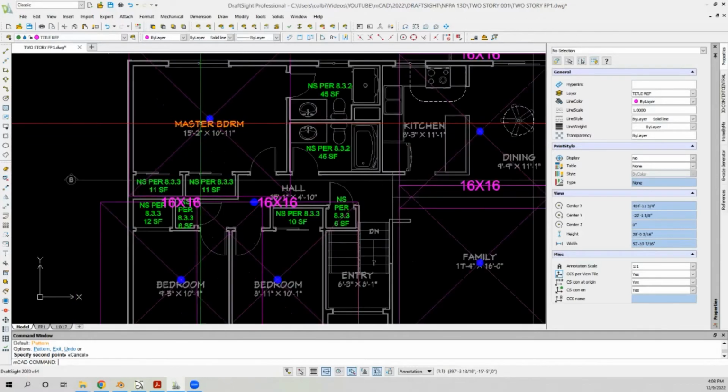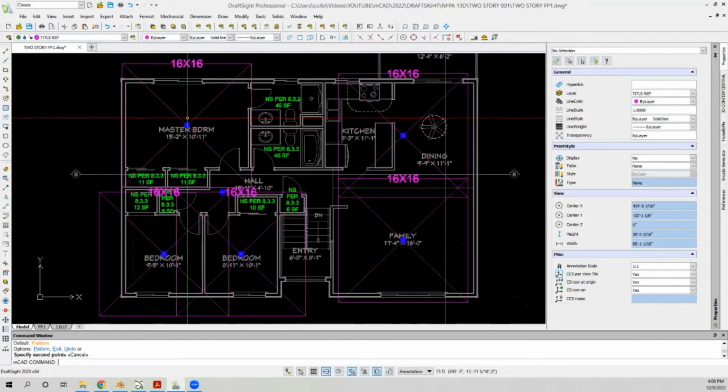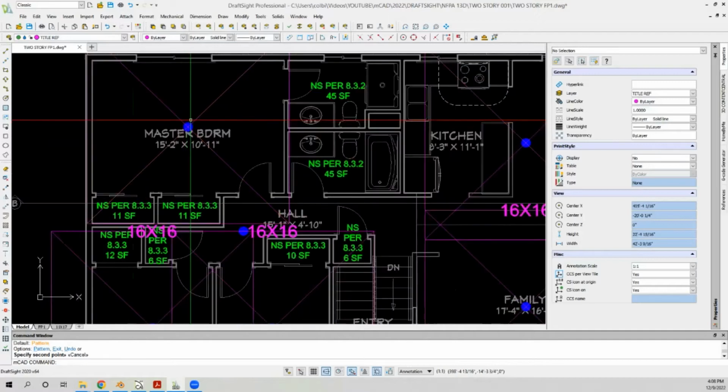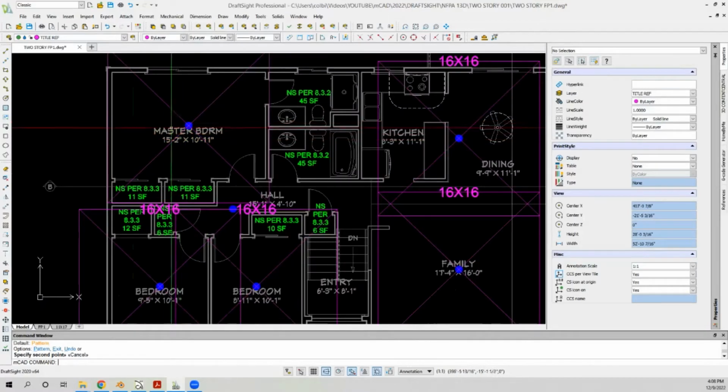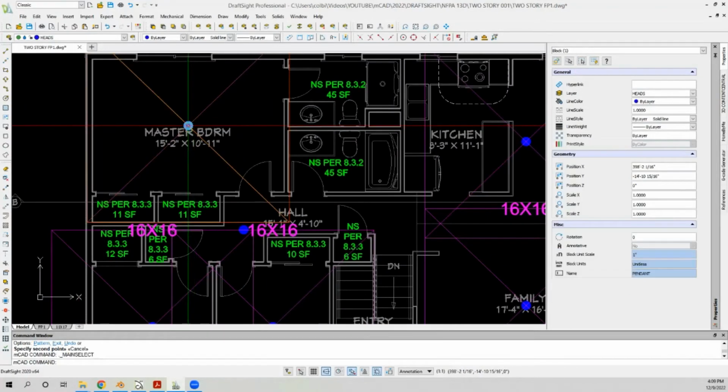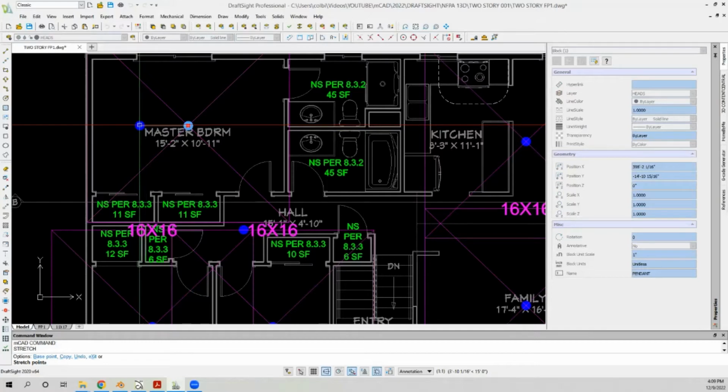Like this shows you that this room is covered, but I know that there is a fan, and it's too close to it, even the regular light. It's 16-foot spacing, and the room's 15.2 across, so I don't know. I would normally, if it didn't show a fan, probably max out the 8 feet from this wall to get it over here, and you'd be far enough away from the light. But since I know it's got a fan, I'm just going to do 2 heads. I'm going to just keep it in the middle to line up with the lights, in case you like that type of thing.